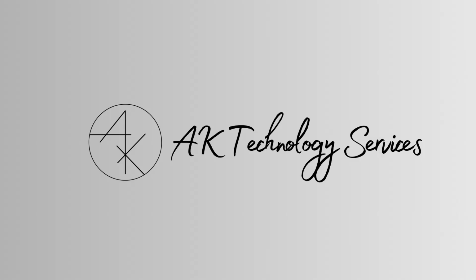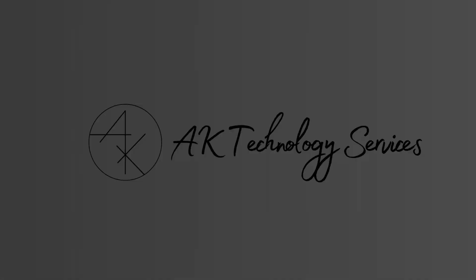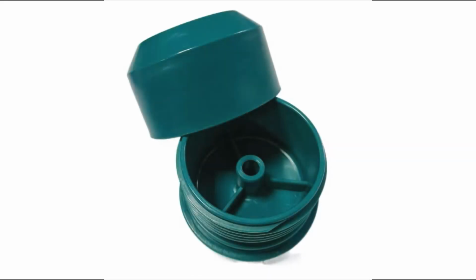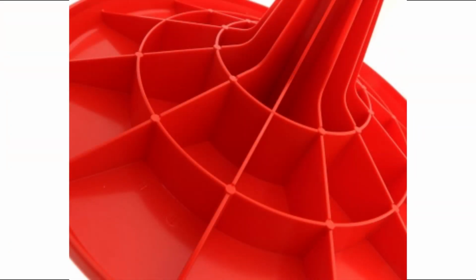So in this video we are going to see how to use a profile rib and trajectory rib in Creo parametric. Before getting into the video, I'd like to give you a small hint about the purpose of a rib. A rib is a structure in a design which is used to give strength to supporting parts, like when you have a boss to hold a stud or a nut and bolt system, then there should be a rib towards it where you can increase the strength of the product.